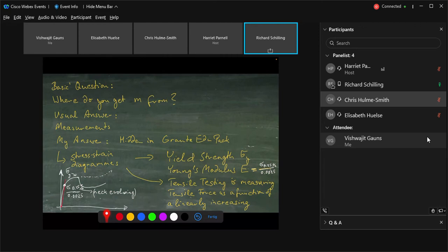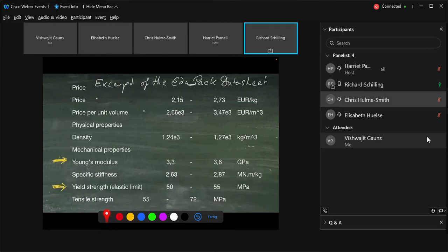You use the yield strength, or the ultimate strength of the material, and the elongation at that yield stress, and then you take the Young's modulus, and then you have two points of your stress strain curve, and you use these two stress strain coordinates which you find in the EduPack to calculate your time dependence, to find this stretched exponential power.